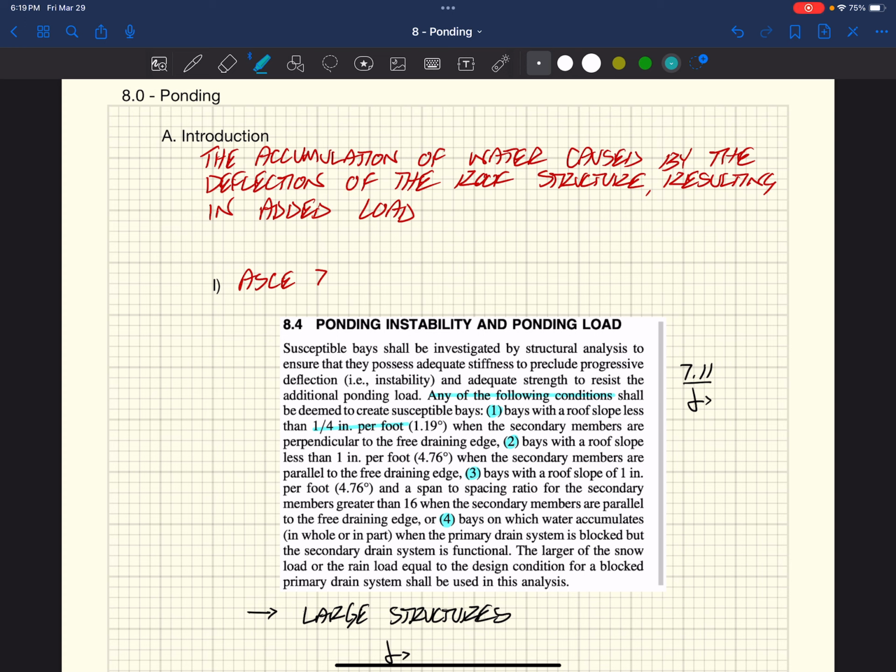Sometimes, as a structural engineer, we essentially dictate the slope of the roof based on the structure being sloped. Other times we're going to run a flat roof and then they're going to slope it with the insulation they provide between our structure and the membrane above. Usually, especially if they do a structure slope, we're definitely going to be at 1/4 inch or more per foot. And as I mentioned, the IBC requires some of that. So that's one susceptible bay.